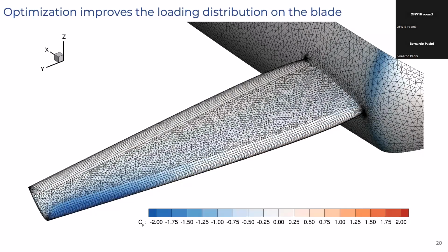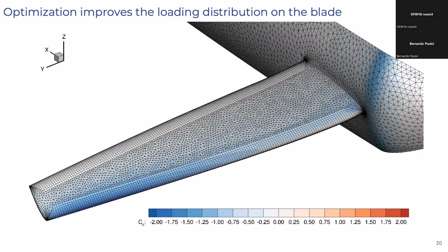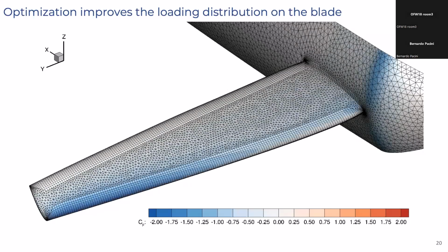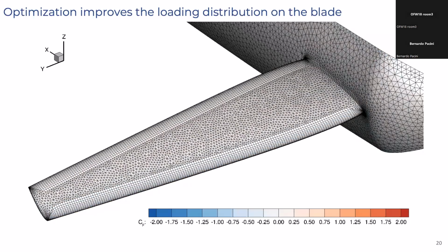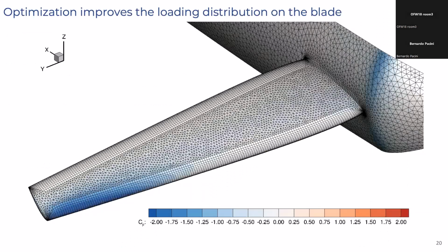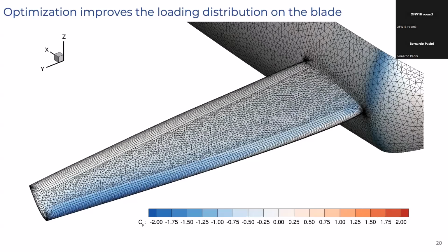Yes. So this MRF simulation is entirely separate from the fuselage simulation or the wing simulation. We do that because we need steady state analysis for optimization. Unsteady is simply too expensive.